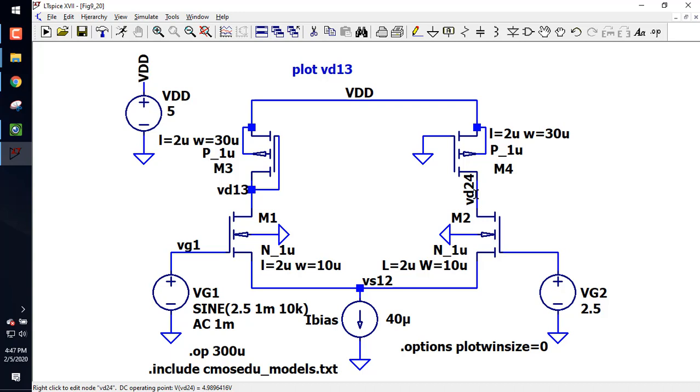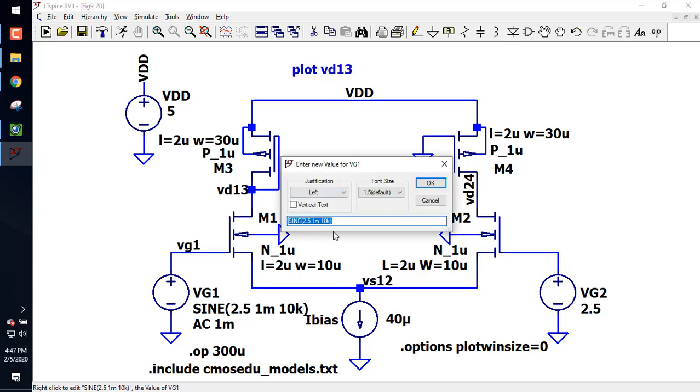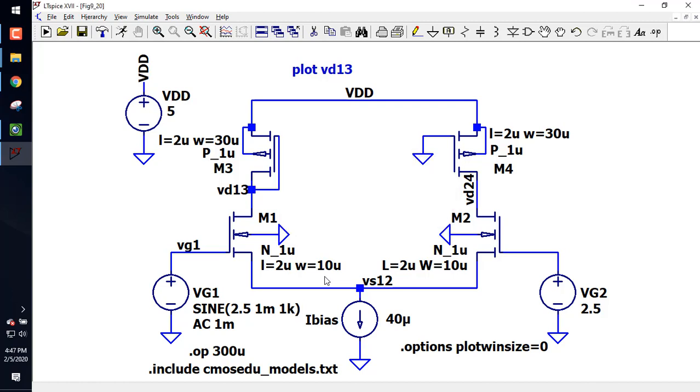So with the AC, I'm going to use the transient, and I put in 10 kilohertz, I guess, and let me change that to 1 kilohertz. Now remember, with transient, it's not like AC. With AC, I could put 1,000,000 volts here and it'll treat everything as small signal. With transient, I have to be careful not to go large signal, because then my approximations are wrong. They start to get even more off than what we had before.